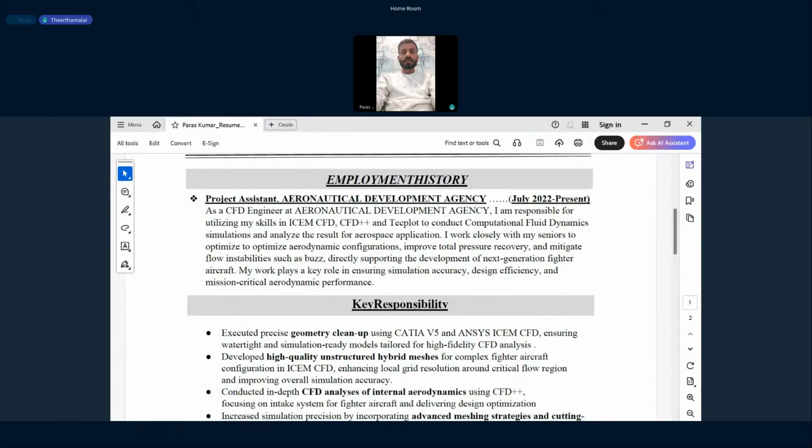But aerodynamically, you have worked on flow and all those. Aerodynamically, what is the benefit of putting the air intake there? Suppose the wing is not there. The air intake is there. The angle of attack faced by the air intake will be the free stream angle of attack, correct? Yes, sir. But in the presence of the wing, how will the flow turn? Will the angle of attack of the intake be lower or upper?